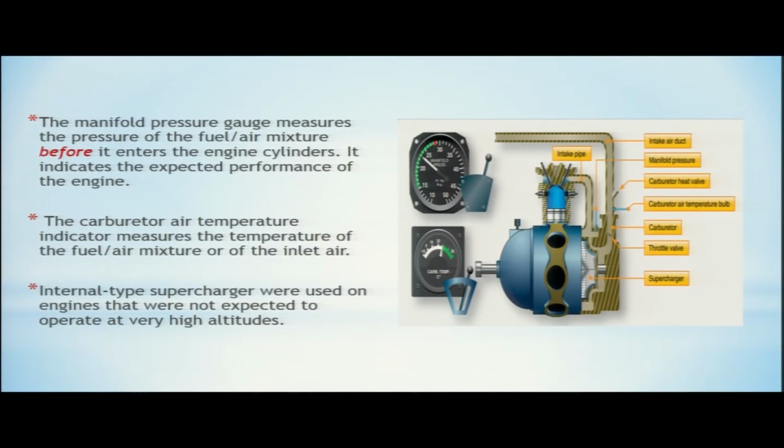Since it is compressed to more than the atmospheric pressure, we want to know what is the pressure of the fuel air mixture which is going inside the engine cylinder. So the manifold pressure is an indication of the performance of the engine. The carburetor air temperature indicator measures the temperature of the fuel air mixture of the inlet air.